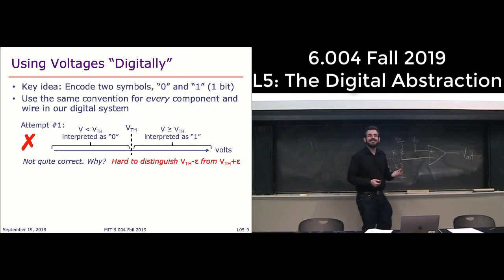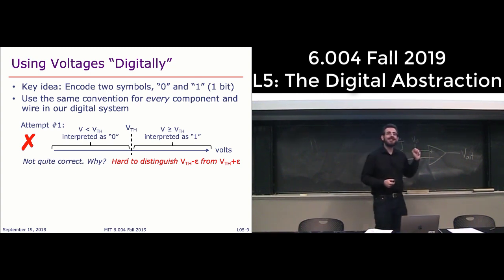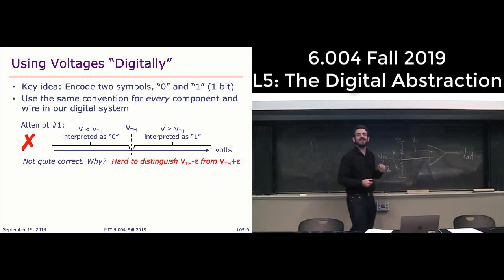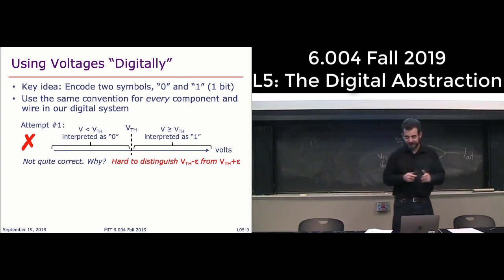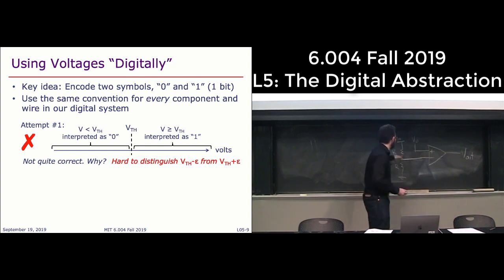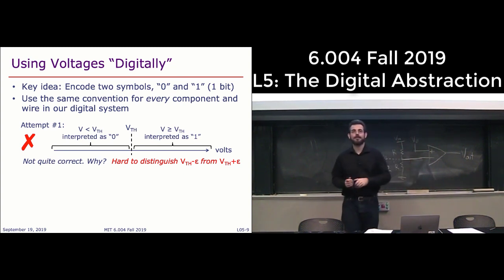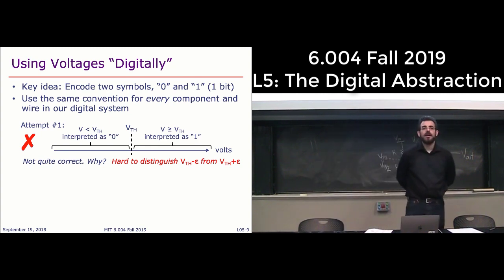Except it's not, right? Except this resistor will be a little bit different, or this resistor will be 0.1 degrees hotter, and that means its resistance is higher. And so this threshold is going to change. And so if you have values that are close to VDD over 2, or your threshold voltage, this is going to oscillate. So again, not a good standard. Okay, any questions?